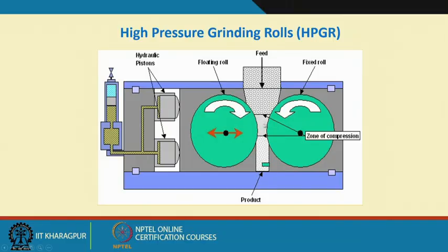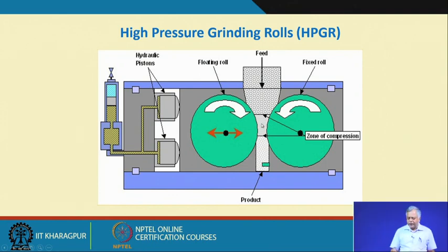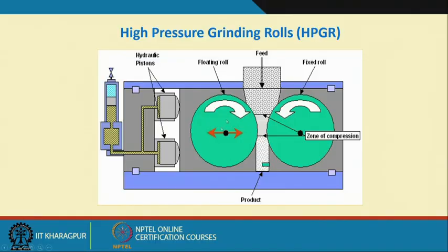Based on that, I can calculate how much compressive force I have to induce through this pressure, and we can calculate the pressure energy and impart that much pressure energy to those particles to break it to exactly what we want, but it may not always be that precise, because the particle characteristics vary from each other.